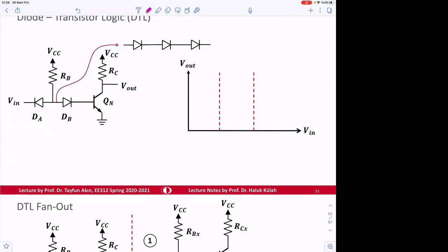So this is also shown in this graph. So by putting here, maybe either here or to this point, 3 of them, let's say, extra 3. So this one is going to be 0.7 volt plus 3 times 0.7. This becomes what? 2.8 volt. That's too much maybe. And this is going to be 2.9 volt. Okay.